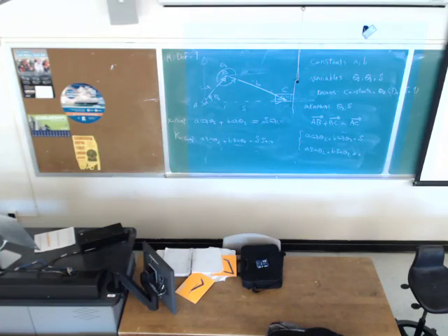Since we don't know which one is our answer, we cannot use equation 2 to solve the system of equations. What we need to do first is get rid of theta 3. I'm going to get rid of theta 3 first, solve for s, then I can find theta 3. If I want to get rid of theta 3, I keep any term with theta 3 on the left side. I keep this on the left side, moving a cosine of theta 2 to the other side. It's going to get a negative sign. And b sine of theta 3 equals negative a sine of theta 2.